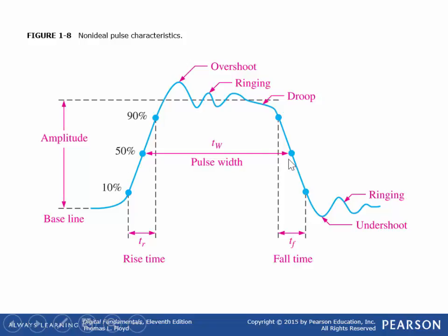The pulse width is measured between the 0.5 points. The rise time is between 10% and 90%. Those are some terminologies that we'll talk about later on. That's in the ideal world. You do have some overshoot and undershoot. This one is actually pretty bad. I don't see very many this bad. The only issue comes in if this ringing is above 0.7 volts, because sometimes it can create problems with the circuit.